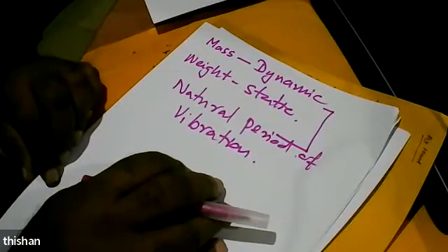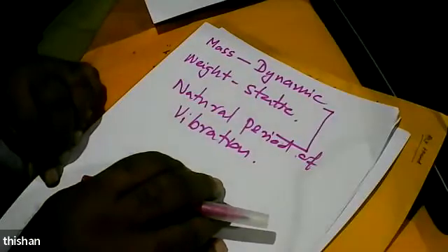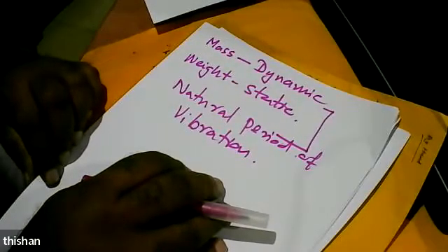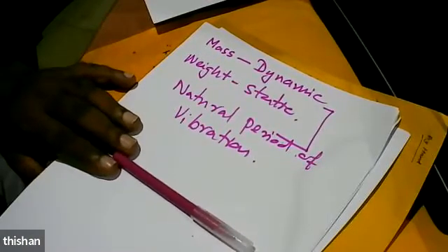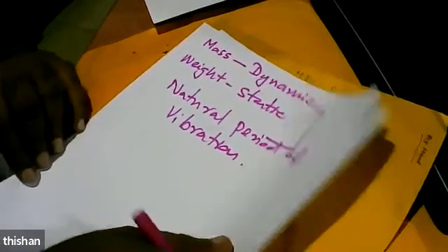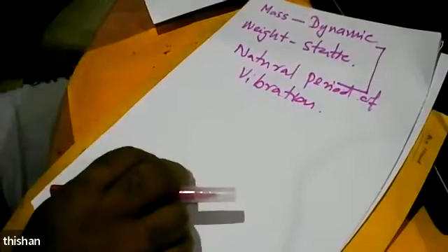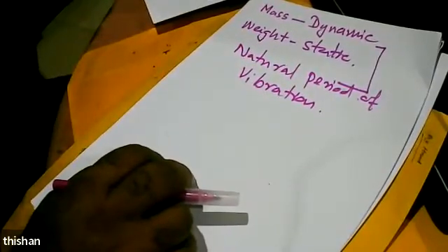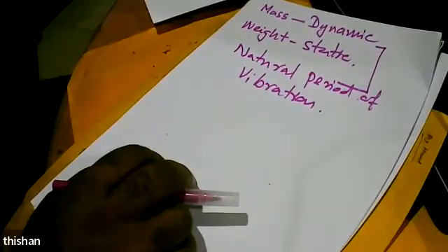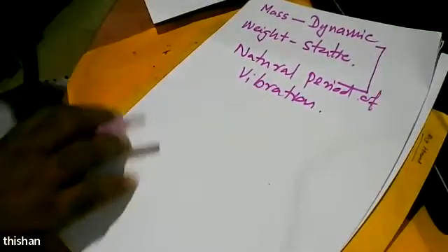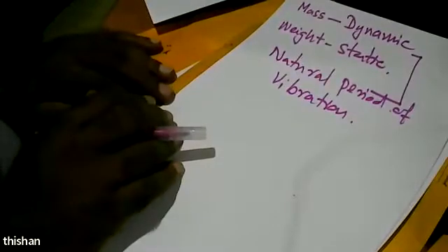But in the actual structure, there is no rigid arm. It's embedded in the beam. So make sure you allocate zero mass, zero weight. The reason for telling this is there may be some structures where you have a number of rigid arms. If you have only one rigid arm, it might not make a big difference in the program. But if you have so many rigid arms, then you have to be careful. So that is one place where you have to be careful. And then what are the other places where you have to be careful?